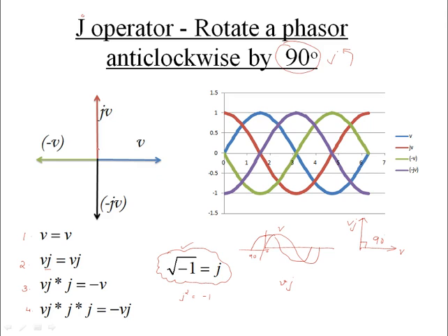Okay, so this is my vector. First multiplication by J like this, 90 again and 90 again and 90, like this. See, this blue vector is represented in the waveform by this. This is my blue vector, a normal sinusoidal waveform. And as I've mentioned, if we multiply it by J, I would get Vj, right? So this is my Vj, leading by 90 degrees. This is my Vj, the red one. Then minus V is this green one, right?